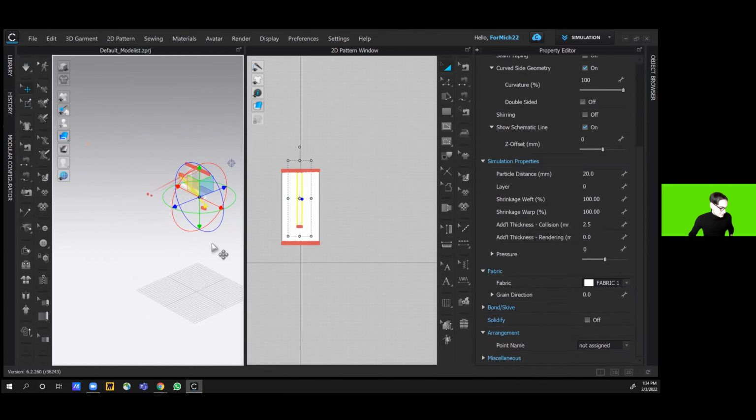different materials that you can use in Clo that have very different physical properties, and you can control it even in terms of the direction in X and Y, or the warp and weft, whether it's stretchy or whatever. The fabric that we're using now, and that is used when you just import or draft a random pattern, is the default fabric, and the default fabric is really stretchy and really thin. Later on, we'll be using the leather again, like we did last week, which is a lot more rigid and a lot less stretchy. And when we use that, I can go into the dialog box again and show you where the settings are to make something more or less stretchy.